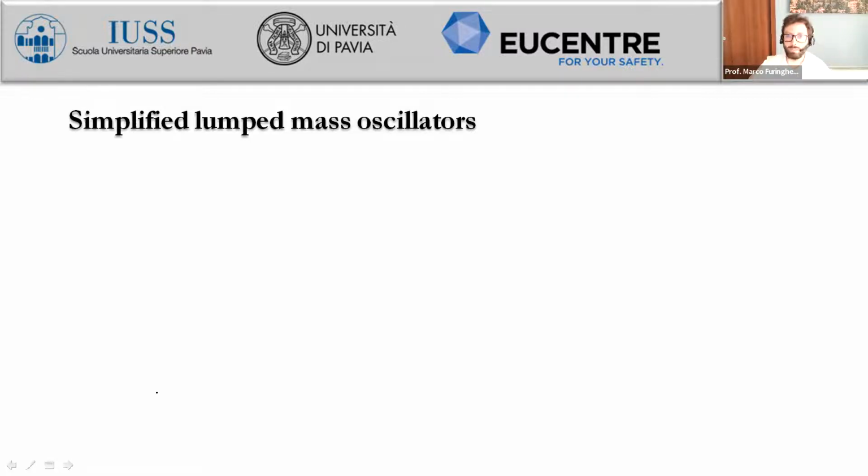And the stiffness can be represented by the stiffness itself of the isolation system. We have to pay attention to these terms. The mass is the mass of everything which is above the isolators. But, as you now know from this course, we have to pay attention to the word stiffness, because the stiffness is generally associated to something linear elastic.